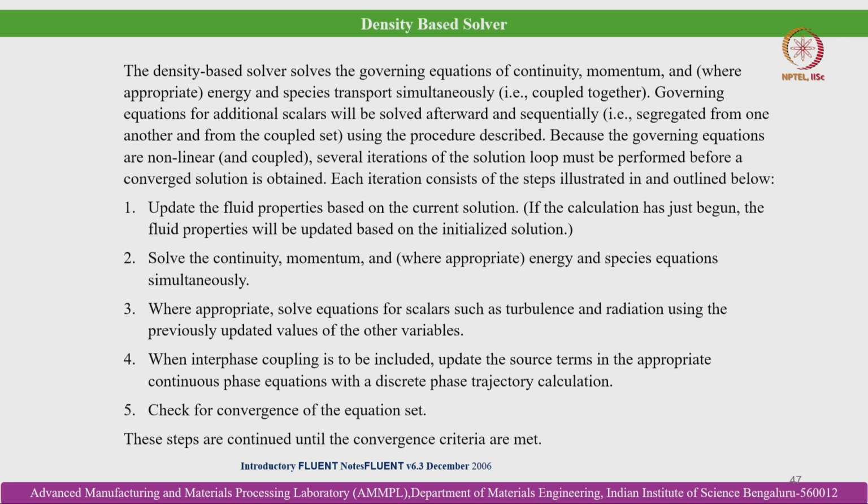So, what is the density based solver? The density based solver solves the governing equations of continuity, momentum, energy and species transport equations simultaneously, coupled together. Additional scalars will be solved afterward and sequentially, segregated from one another and from the coupled set.